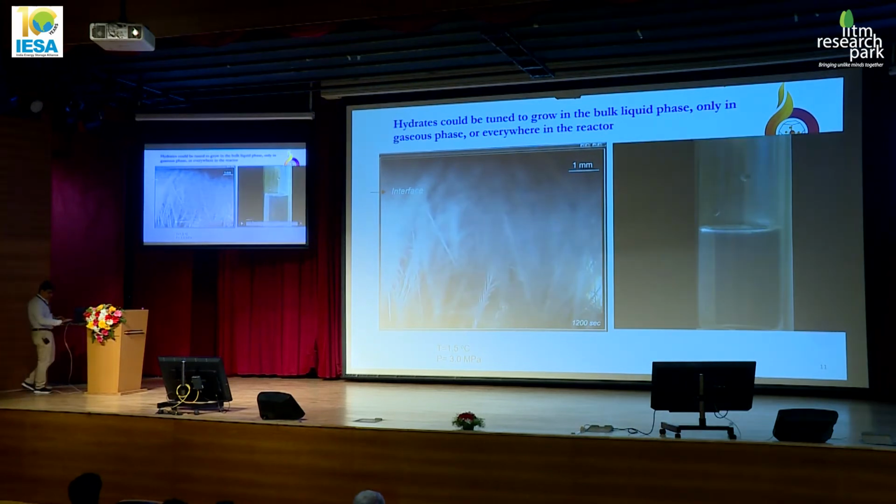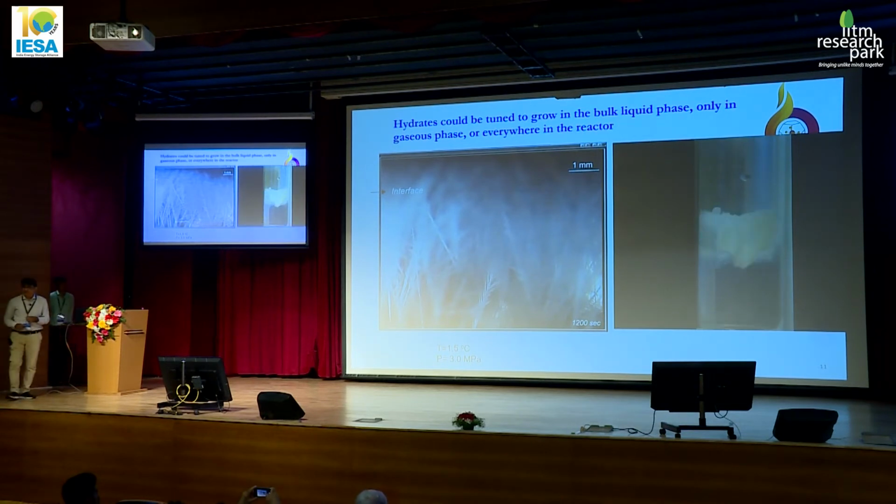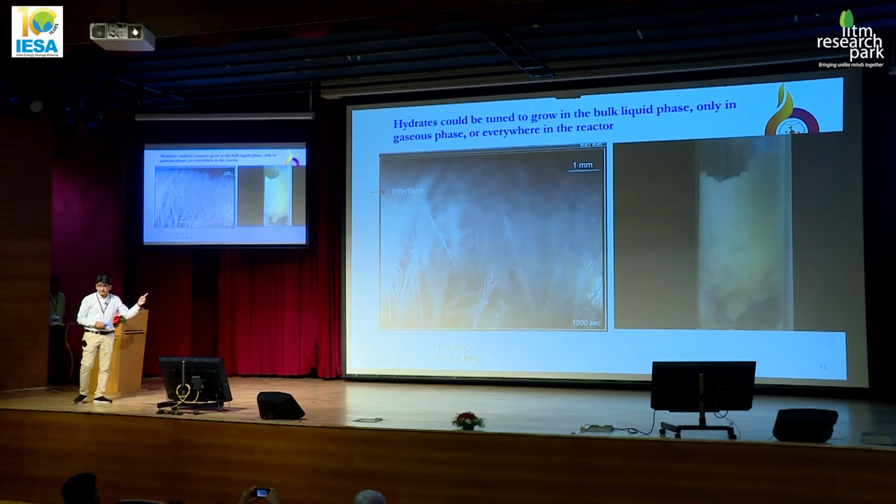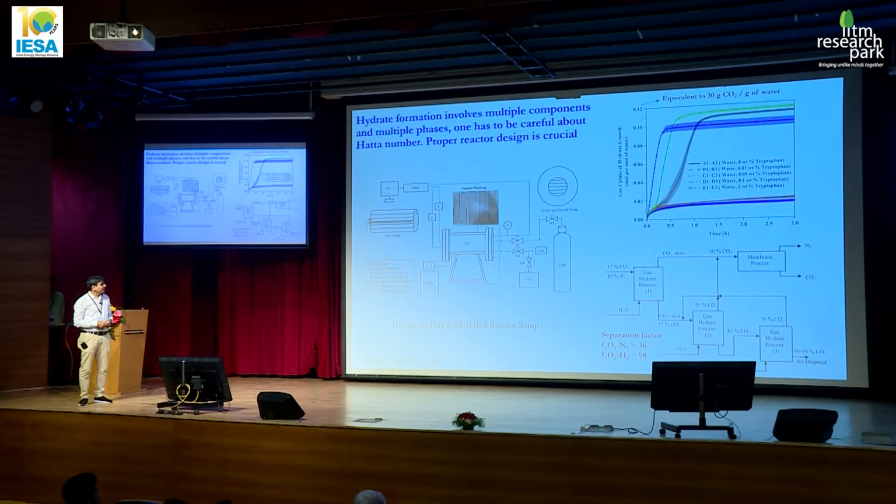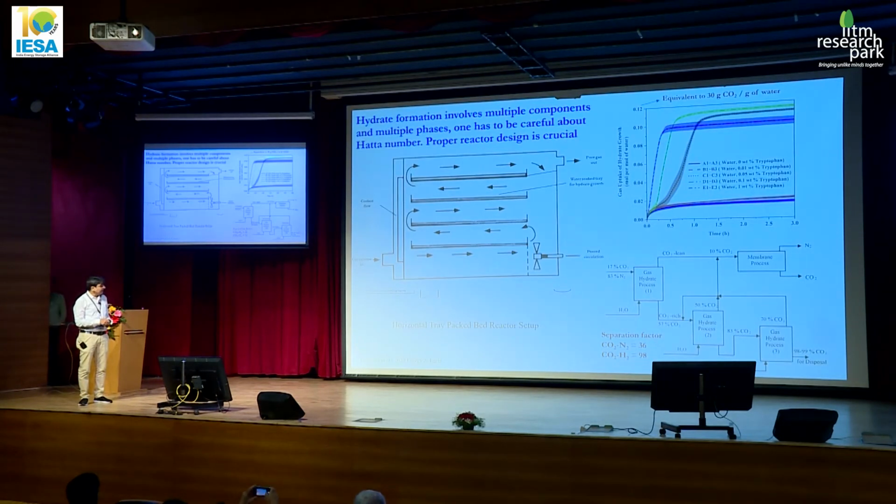So if you see this particular slide, it took 1200 seconds, but in this particular slide, you will see these hydrates form within a fraction of a minute. The entire water will get converted into hydrate, in what is basically an unstirred reactor. So we have developed a process with a multi-bed reactor.